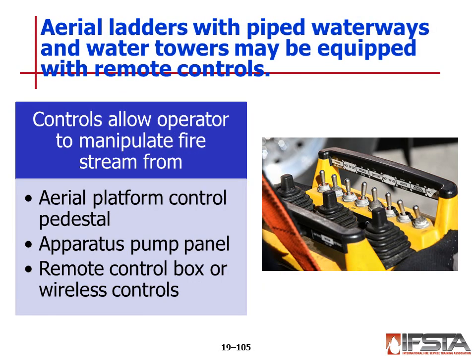Aerial ladders with piped waterways and water towers may be equipped with remote controls that allow the driver operator to manipulate the fire stream from the aerial platform control pedestal, the pump panel of the apparatus, or from a remote control box or wireless controllers. Typically, using these controls, the driver operator can change the fire stream pattern and direction.